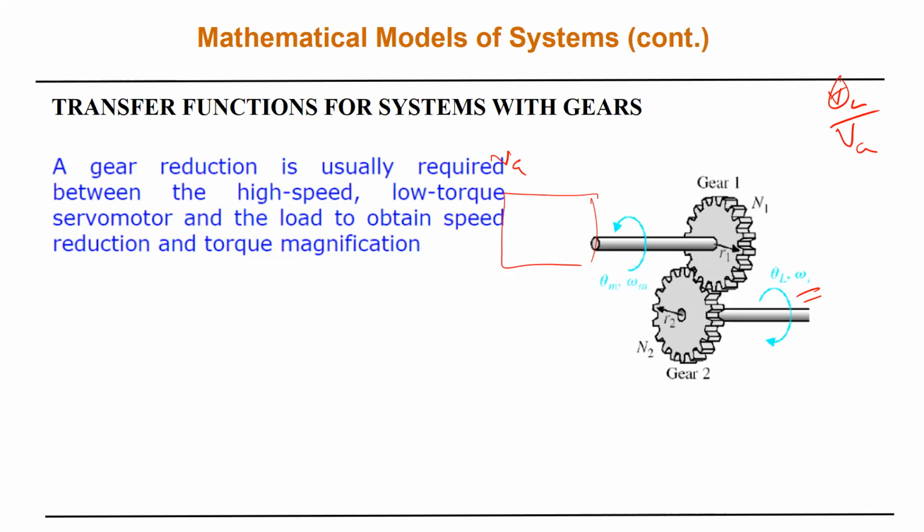Again, why do we step voltage up? For distribution purposes, we need to step it up to avoid losses. Exactly. In the power system, in the transmission line, if the load is far away from the generation, you try to step the voltage up.